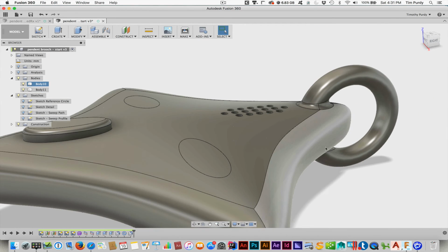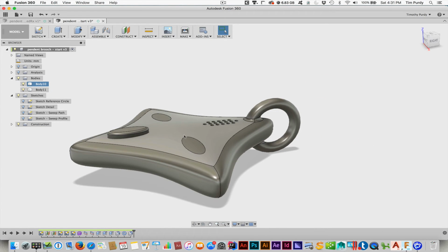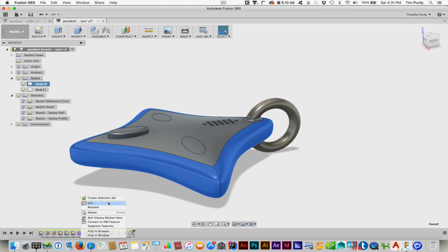So that's a real quick demo of what a T-spline form is. As long as it makes a properly closed watertight form, it'll convert to a solid, and then, as you demonstrated here, you can use the standard set of tools to go through and modify the form. Okay, if you ever need to adjust it, you go back here in the timeline, right mouse click and say edit, and you can continue to sculpt on it. It doesn't keep the history within the T-splines, okay? Only in the modeling side does it keep the history or the timeline, so just be aware of that.